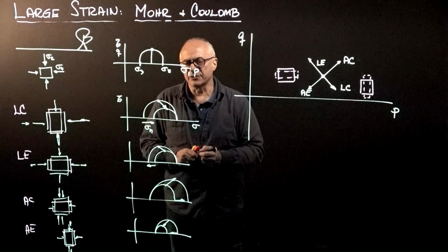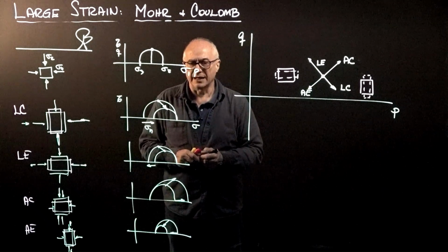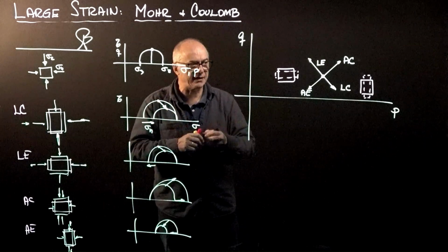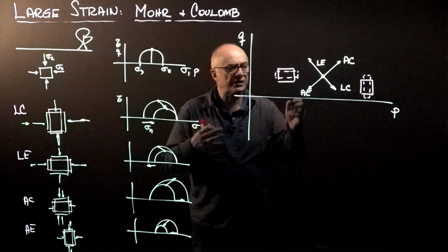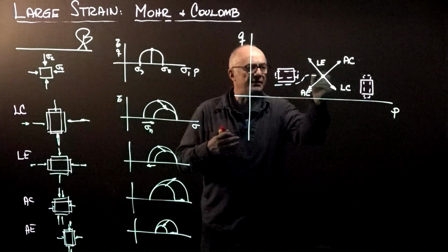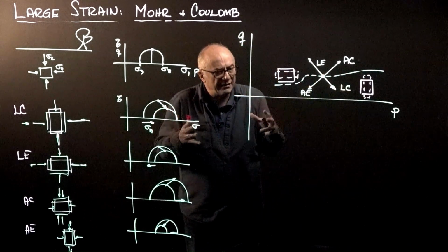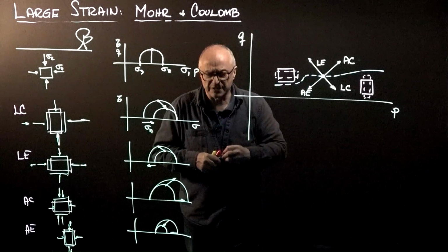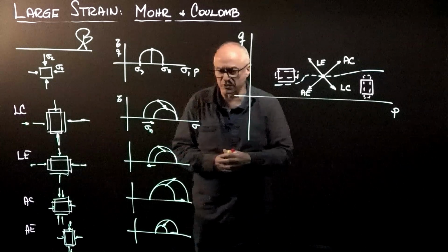These are the four classical stress paths, and they evolve differently in the tau-sigma and Q-P space, but it is important to realize that the deformations are also going to be quite different, from getting taller and thinner or shorter and fatter in the different regimes, under those stress conditions without additional boundary controls.